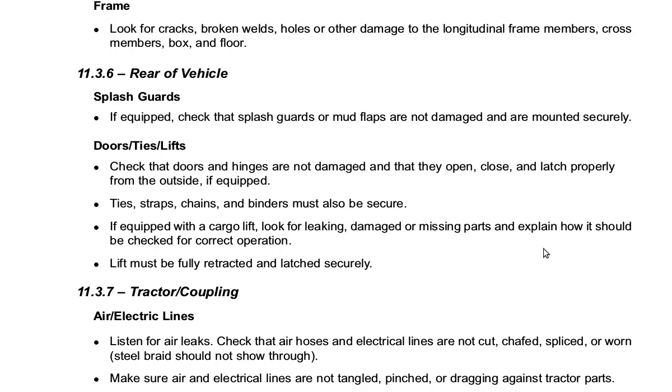Rear of vehicle. Splash guards. If equipped, check that splash guards or mud flaps are not damaged and are mounted securely. Doors, ties, lifts. Check that doors and hinges are not damaged and that they open, close, and latch properly from the outside if equipped. Ties, straps, chains, and binders must also be secure. If equipped with a cargo lift, look for leaking, damaged, or missing parts and explain how it should be checked for correct operation. Lift must be fully retracted and latched securely.